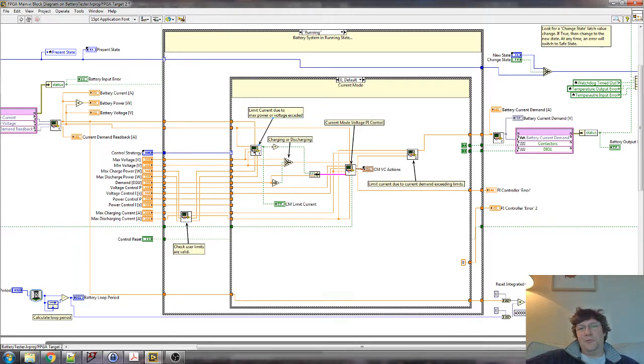If you want, it can be a 14 volt lithium or something like that, that's fine. 12 volt lead battery, and we've been charging for a long time, and we have, say, I don't know, 50 amps charging. We've been doing it for 10 minutes maybe. If it's a 50 ampere hour battery, then chances are the voltage is going to be rising quite a bit now, unless it was empty to start with, of course.